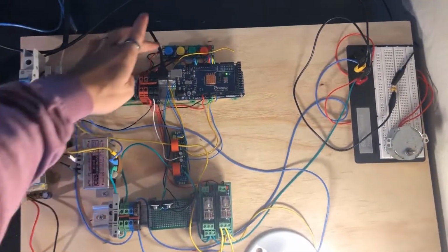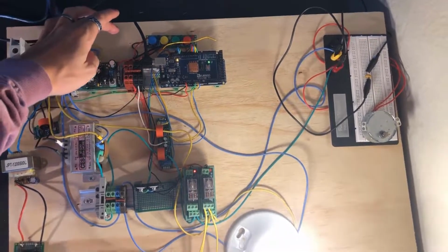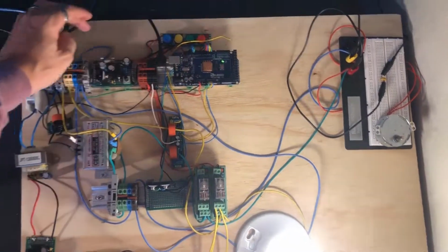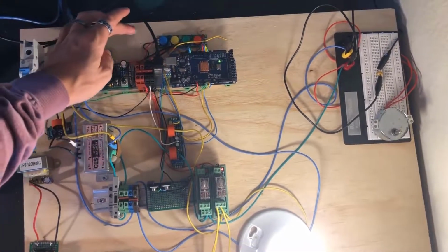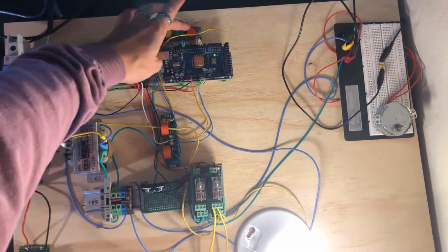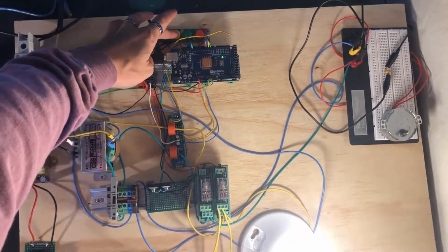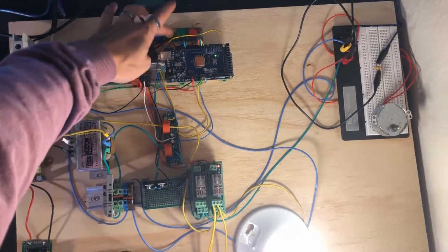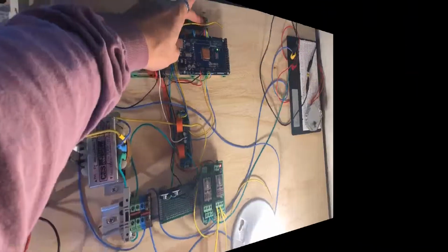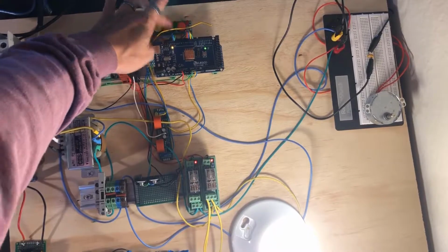I hit fault 3, which turns the motor off as intended. Then I reset the fault. I then hit fault 2, which disrupts the utility power, and the inverter is now supplying power to the residential load. The transfer worked flawlessly, with the only indicator being a flicker of light due to the transfer time. I reset the fault, then test the critical fault, and the inverter does its job again and keeps the residential